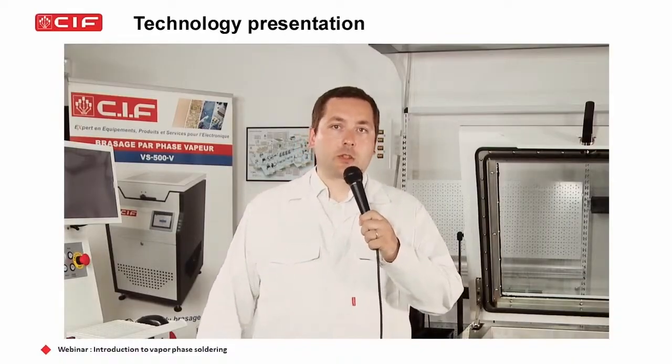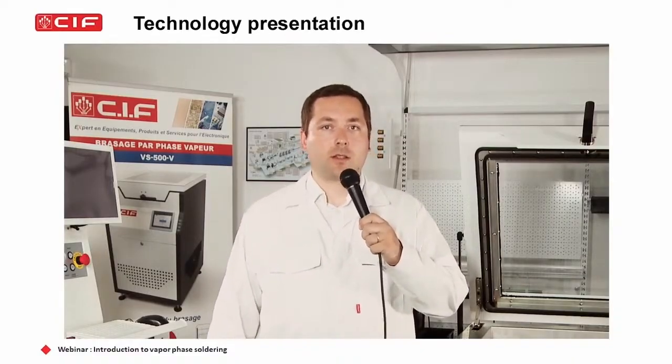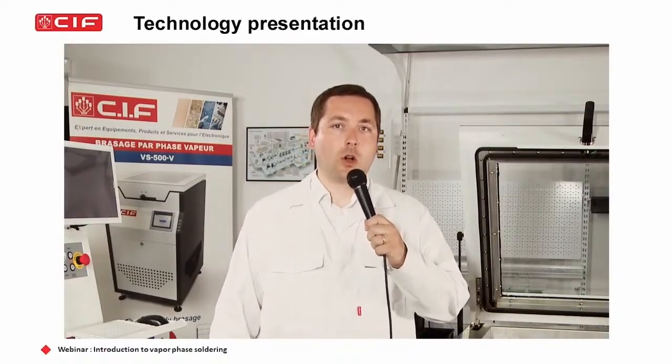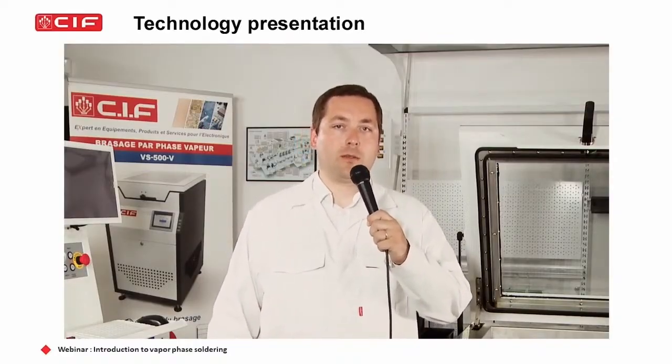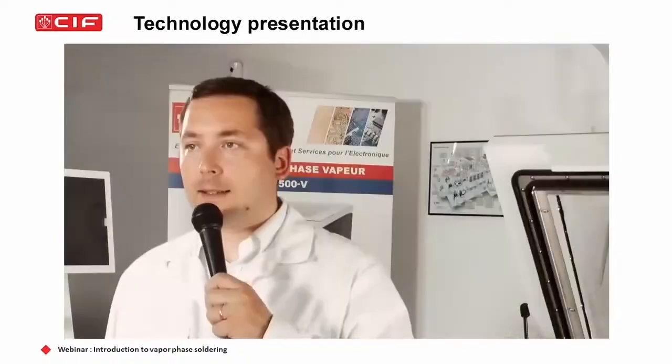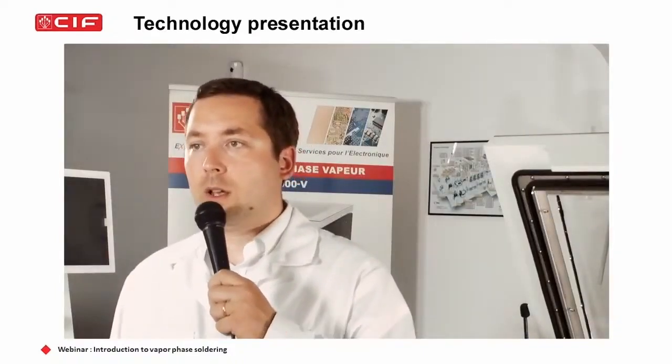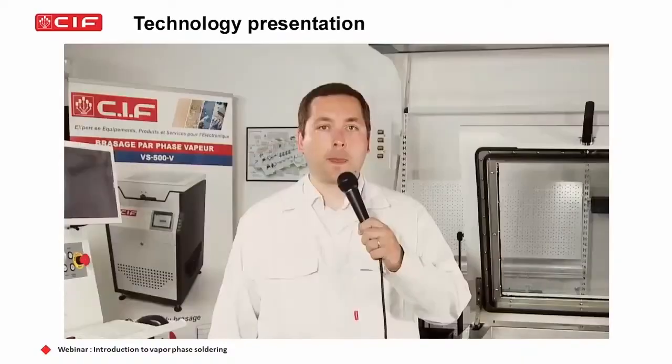By controlling in the chamber the pressure and the temperature, we can reproduce the exact same conditions over cycles with very high precision. This ensures for you a consistent solder joint quality on every board.